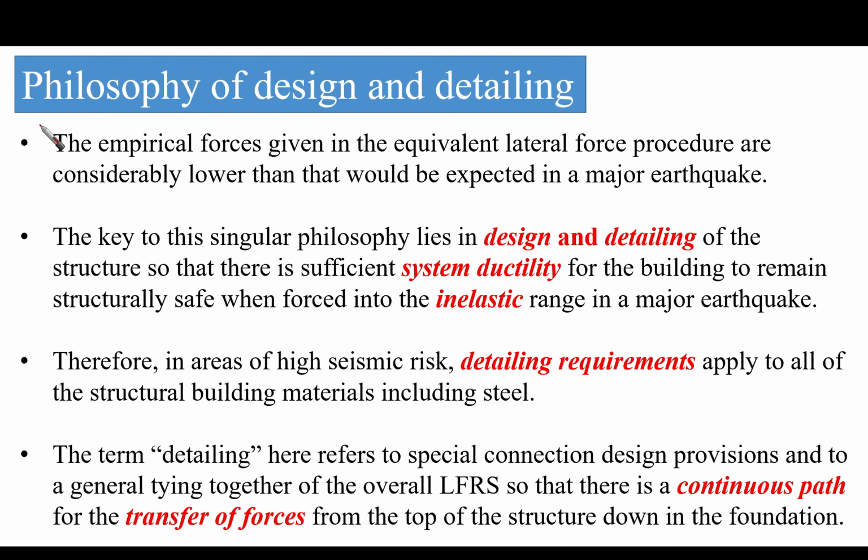Now let's talk about the philosophy of design and detailing. The empirical forces given in the equivalent lateral force procedure are considerably lower. Look at this point: lower. This word is very important. Lower than that would be expected in a major earthquake. Well, it is a big question mark here.